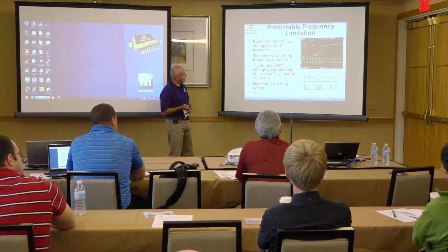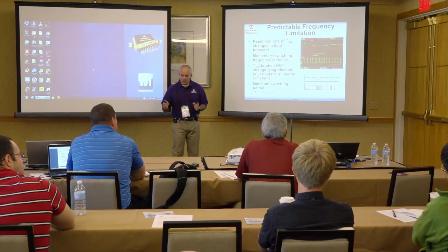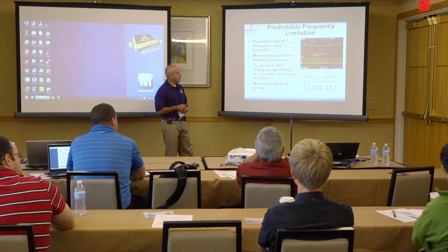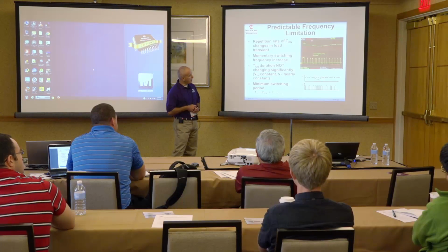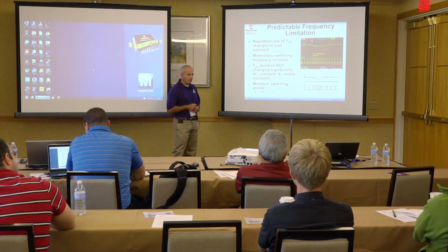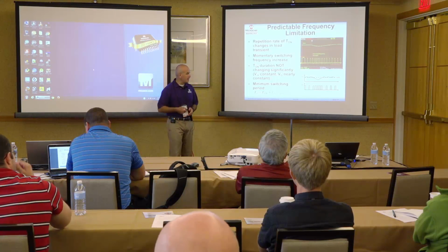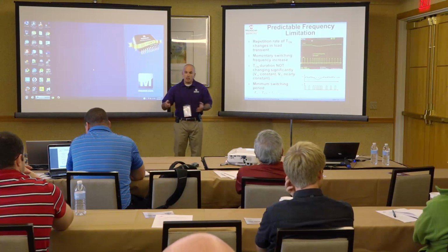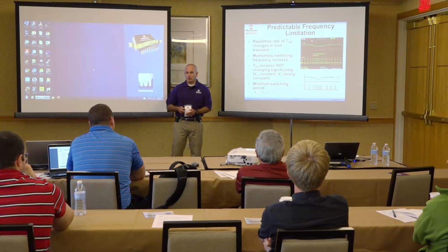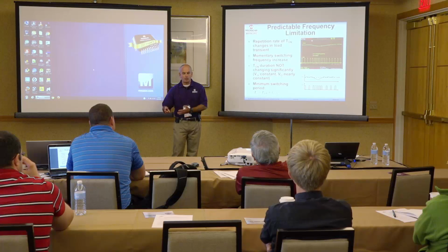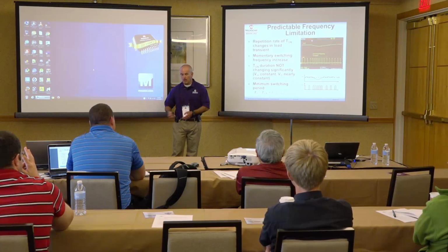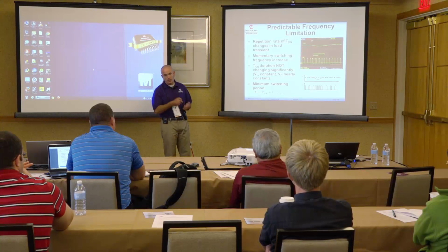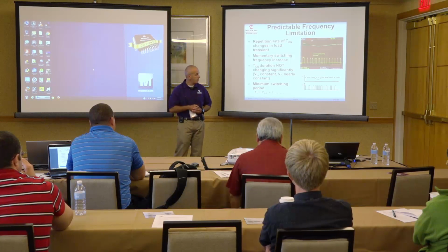So during a load step, you basically increase momentarily the pulse density, the repetition rate of the on time. You have this momentary switching frequency increase, and this scares a lot of users because many users are concerned about EMI spectrum or frequency variation.